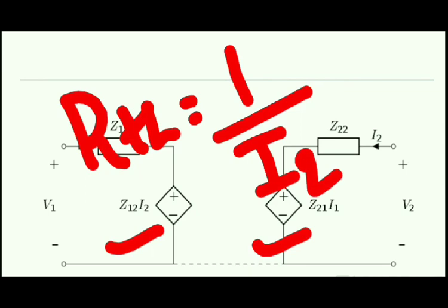So if we are able to calculate the ratio of 1 upon I2, we can easily comment on the R Thevenin, and load resistance is equal to R Thevenin. The only procedure to calculate R Thevenin is such that we have to place a battery of 1 volt and consider the ratio of voltage and current like this, when we are having dependent sources in the circuit and independent sources as well.